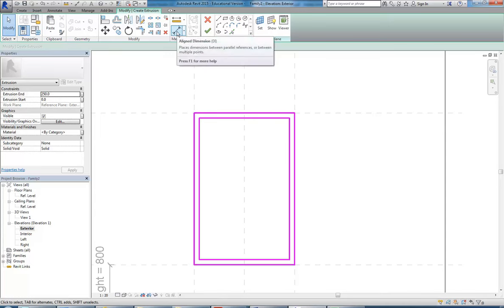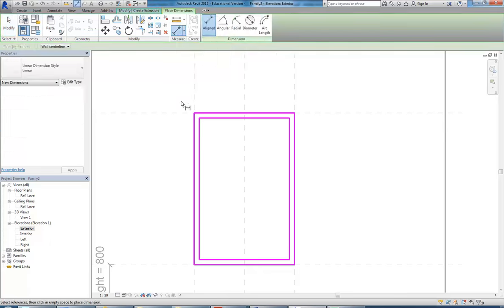And so here I'm going to draw a dimension, and I'm going to just draw it from the outside edge, which we know is locked to the opening, and I'm going to then dimension to the inside, place it up here, and then I'm going to lock that dimension. So that means as the edges of the opening move, these inside edges of the frame are going to stay 50 mil from the outer edge.